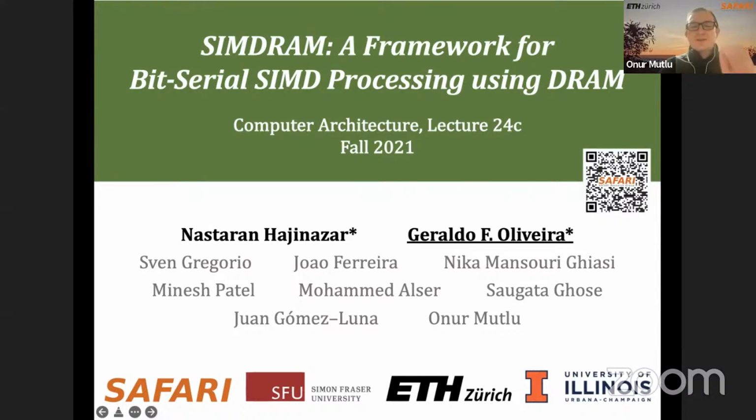I think these two different kinds are important to distinguish and also enable efficiently going into the future, especially if you want to do reduction operations, for example, across different banks. You will need to do that in some place, right? And the memory controller is one place. Or if you have 3D stacked memory, the logic layer is also a place. But still, you can improve the efficiency of those operations, certainly.